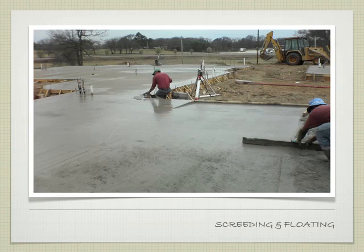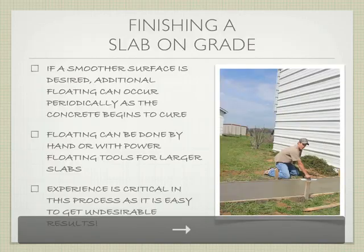So a lot of times in concrete, it's worked in stages across the site. It's a continuous pour, and you'll start at one end and start pouring and screeding. By the time you're pouring and screeding the other end, someone's already doing the initial floating on the first part. So it's a very time-sensitive thing, and it's a progression. It's not that you pour, you float, you move. No. You start pouring, you move the pouring all the way along. At the same time, somebody's coming back behind you, doing the floating and moving forward.